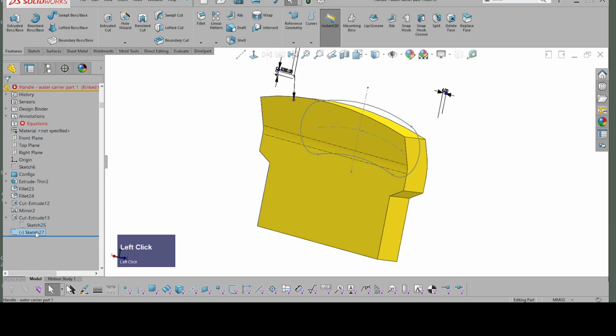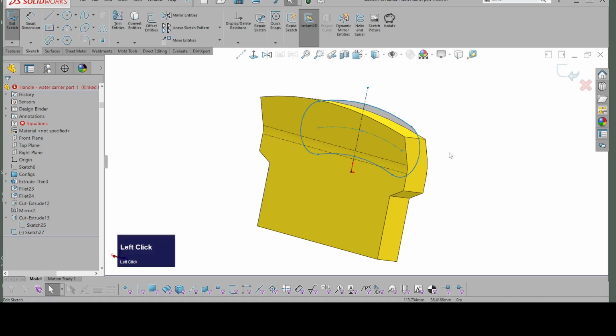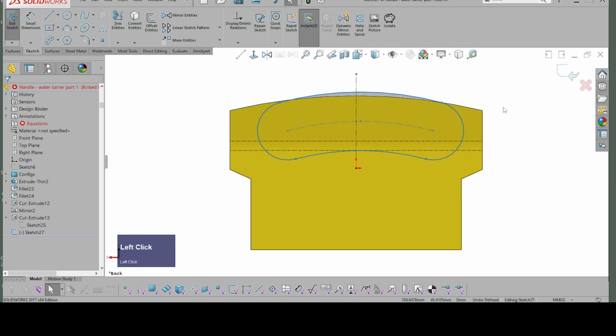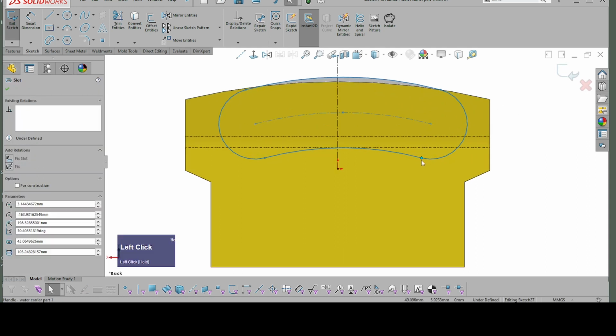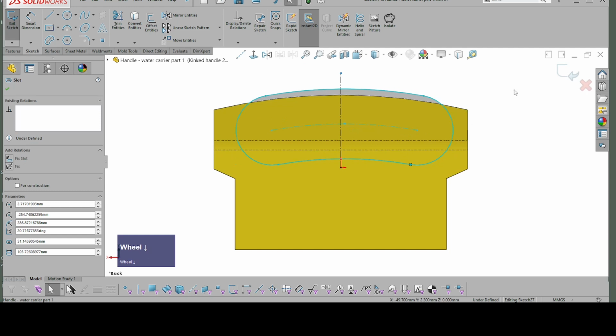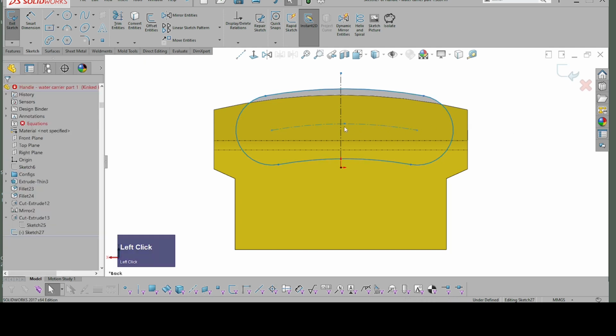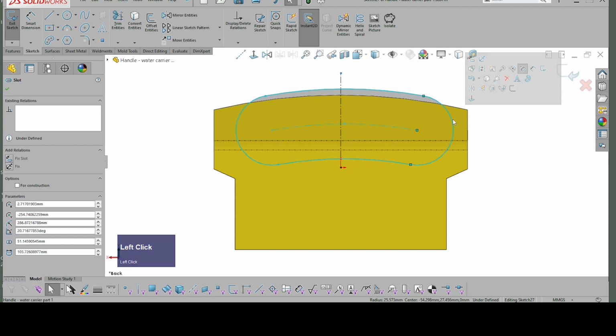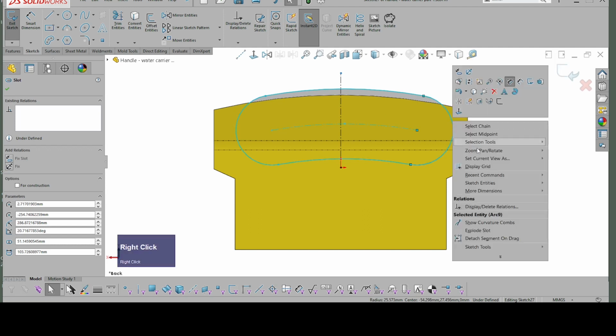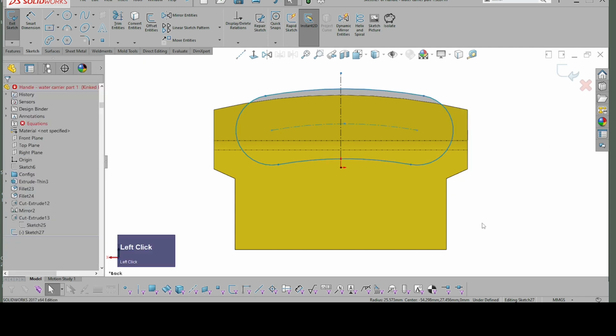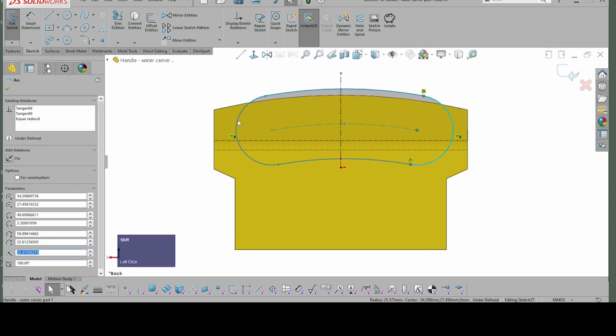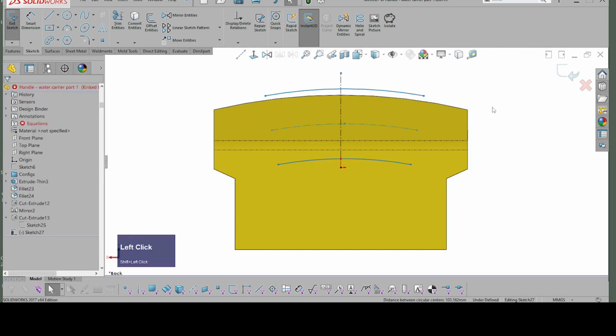Right, so that might make it easier to manage because it's less likely to get connected to points that I don't want it to get connected to. Right, so at the moment I can't do much with this that I want to do with it. Because it is currently a slot, if I select a line, it selects the whole thing, okay? So the way to get around that is to right click on it, once you've selected the sketch, go down to this command explode slot, and now it is just a mere sketch. It is no longer a slot.